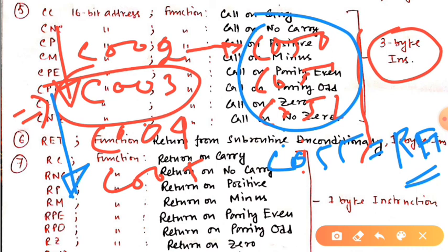it will read the memory address that we have stored in the stack memory during the execution of the call instruction, which we have written in the memory locations C000, C001 and C002. Using these three memory locations, we have written the corresponding address of the memory location C003 in the stack memory.